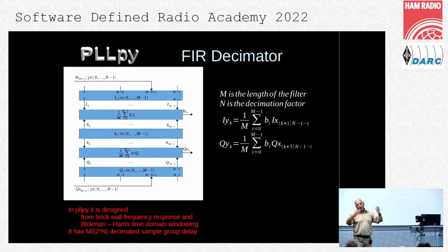We have to use a vector whose length is equal to the filter length, which has to be higher than or equal to the decimation factor. In that, I store the necessary samples for the convolution, and do the convolution only if I have to output a valid output sample.